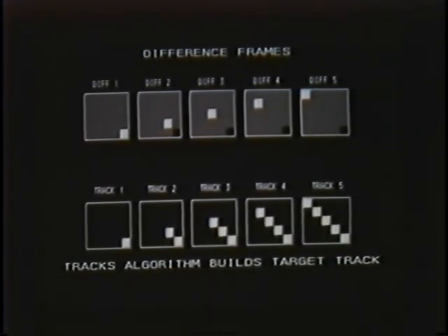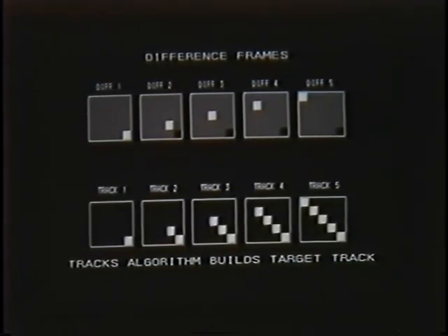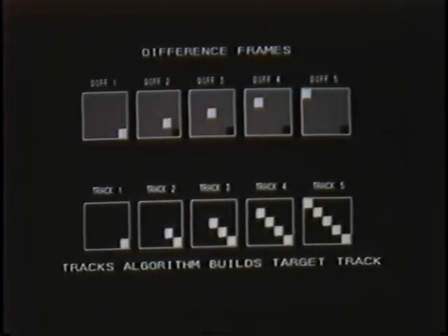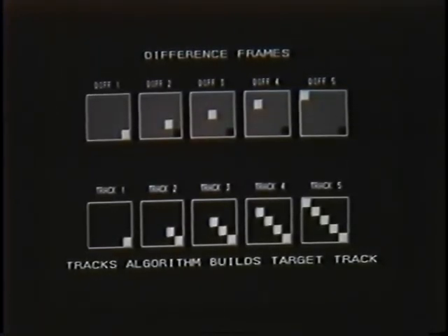the target track. In cases where enhancement was insufficient, and as a result, clutter leakage is extreme, the tracks algorithm may be misled to follow false tracks. When the tracks algorithm first begins analyzing a sequence, it will usually attempt to follow several false tracks. But these should be eliminated as more information becomes available in subsequent frames. Ideally, only the true target will have had the consistent strength to remain once the entire sequence has been analyzed. If false tracks remain at the end of the sequence, then the target is considered undetected.